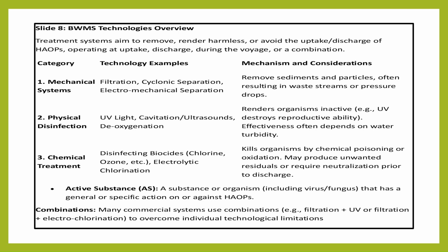Equipment emitting dangerous gases or liquids must have at least 2 independent means of detection and shutdown. For systems that could emit dangerous gases, gas detection by redundant safety systems is required, activating alarms locally and at the control station in case of leakage.